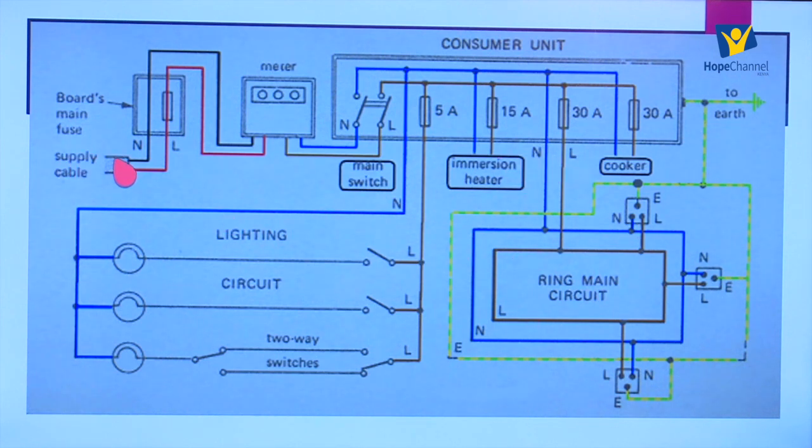So the power has come from the power supply. We have a neutral, we have a live. So the live wire is the one which is passed through the fuse. Usually the fuse is installed on the live wire. Fuses are not put on the neutral wire. Again, we mentioned that the live wire is the one which carries the potential. So there's no potential on the neutral wire, and so there's no fuse there.